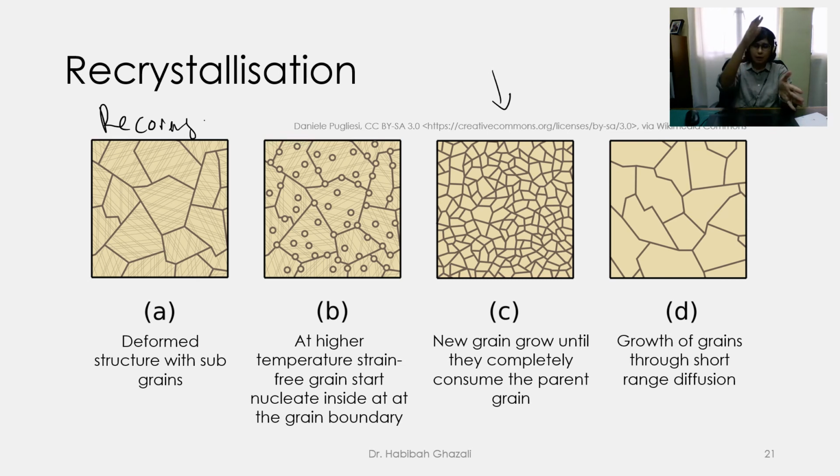Depending on your cooling rate, we can make the size of the grain grow bigger, or if we cool rapidly, it will stay at that size. So depending on what we want to do next, we can make the grains grow bigger, or if we want to have good tensile strength and yield strength, we can cool them rapidly.